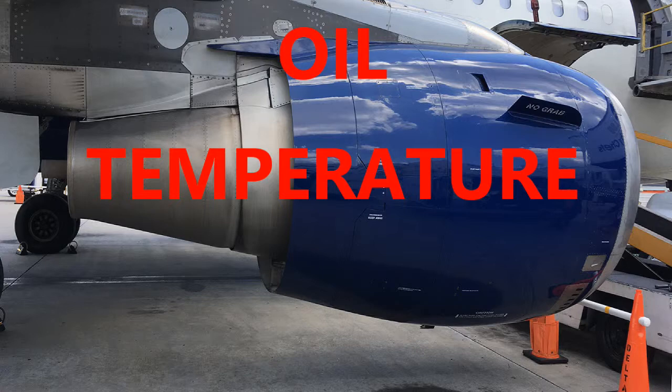Here you have a single element that's sensing the oil temperature. We can get into the electrical part of it, but this element basically causes a change in resistance. When the temperature changes, it's sensitive to that and gives an indication on the ECAM. The temperature measurement range of this element is between negative 58 degrees Fahrenheit and 392 degrees Fahrenheit. It's a pretty wide range.